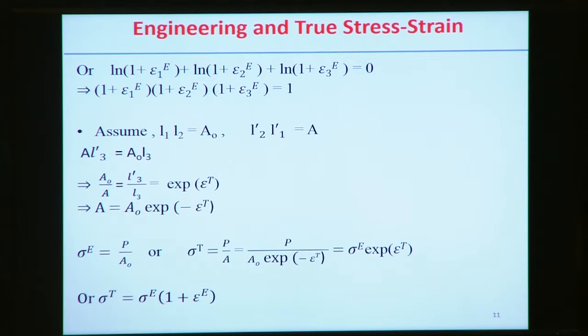Now similarly, true strain equals the logarithm of 1 plus engineering strain. So in terms of the engineering strain, we can find out the product of these terms is equal to 1. So that's the relation that holds in terms of the engineering strain when we assume that there is no change of volume during plastic deformation.